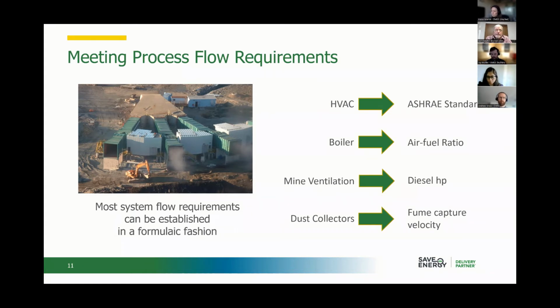But in recent years, there's been a move towards doing things like what they call VOD, ventilation on demand. And so that would relate to moving the amount of air that satisfies various sensors in the mine, whether or not those sensors are temperature or carbon monoxide or dust or whatever else. Some of that works fine. Some of it doesn't work as well as you want.